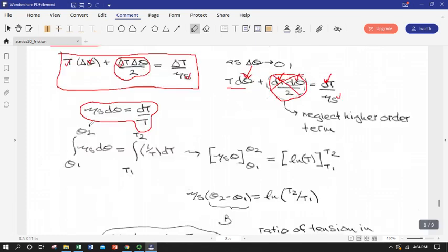Any of you who have taken integral calculus will know, aha, this is easy to integrate. That's great because we're going to use integration of this expression to add up the tension changes. This is a change in tension divided by tension at any point as we add up all the bits of angle from one point to another point that's the end of our total number of wraps. So we're going to add the d thetas up over our entire beta arc that we defined at the beginning. So I'm going to integrate this expression. I'm going to add up those bits of angle with an integral.